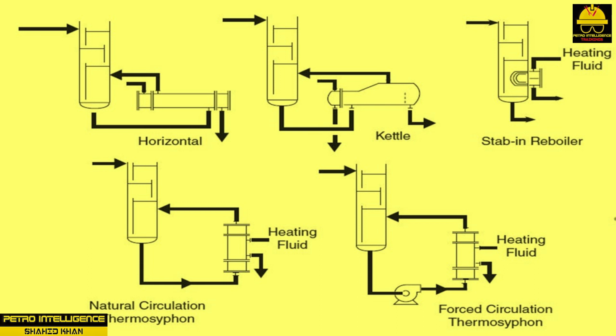A thermosiphon reboiler is a fixed-head, single-pass heat exchanger hooked up on the side of a tower to add additional heat to the process. One side of the exchanger is used for heating, usually with steam, the other side takes suction off the tower. Thermosiphon reboilers come in vertical or horizontal designs. The lower leg of the exchanger usually takes suction at a point low enough on the tower to provide a liquid level to the exchanger.